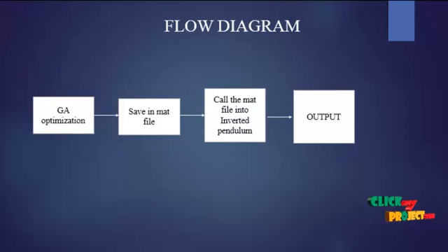The inverted pendulum control is split into two main phases, the swing-up phase and the stabilization phase. The former uses a nonlinear controller to swing up the pendulum, keeping the cart within a limited travel range on the rail. The latter uses a linear state feedback controller to stabilize the pendulum in the inverted position once it approaches the upper unstable equilibrium point.